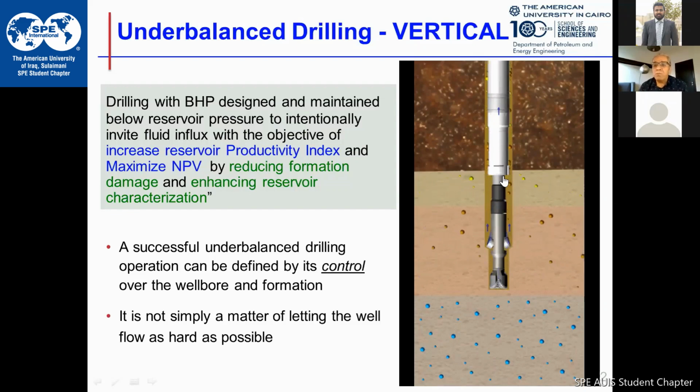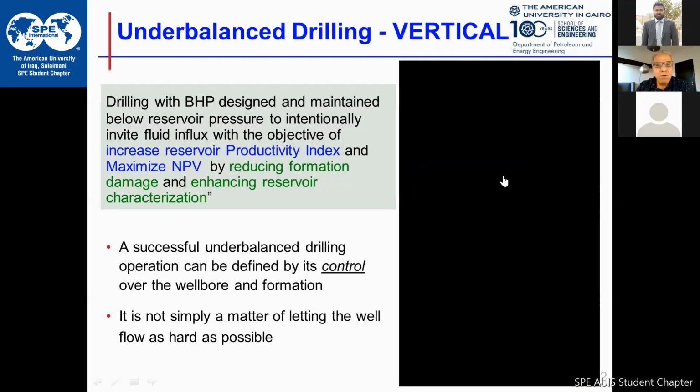Now when we need to pull out of the hole, eventually we can pull out of the hole neatly. There is no damage whatsoever. Hydrocarbon flow eventually prevented mud cake layout, okay? So there is no mud cake, the hole is very neat. The next step to be taken for completion, to complete the well, then the well can be completed right away with an open hole or cased hole. And there is no need to clean up or stimulate the well.